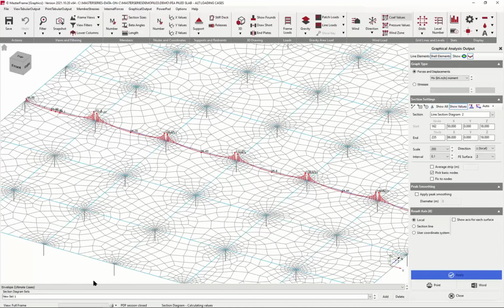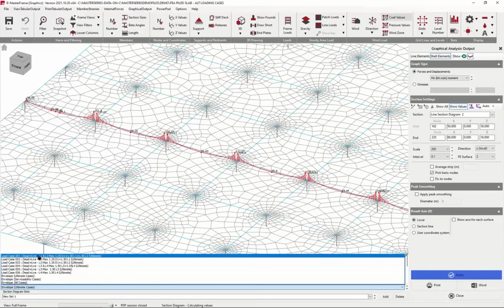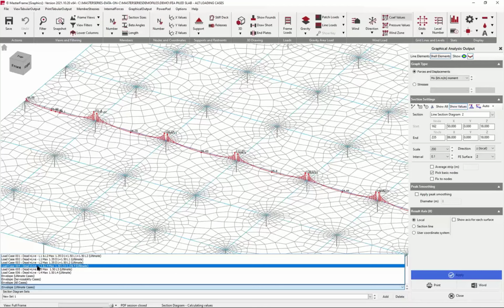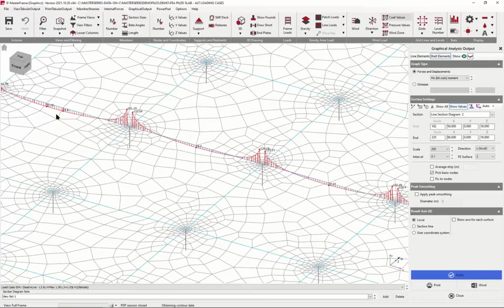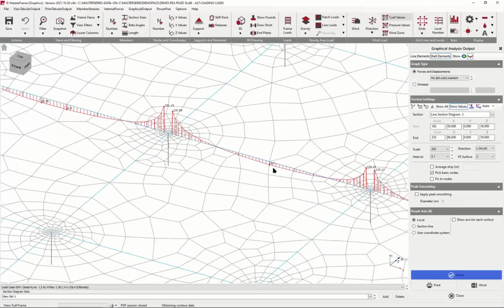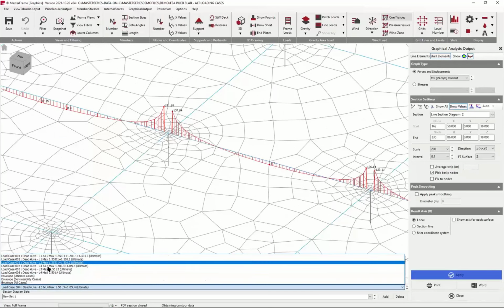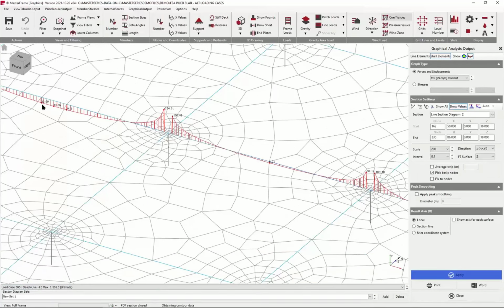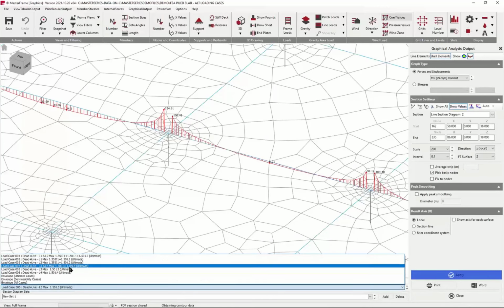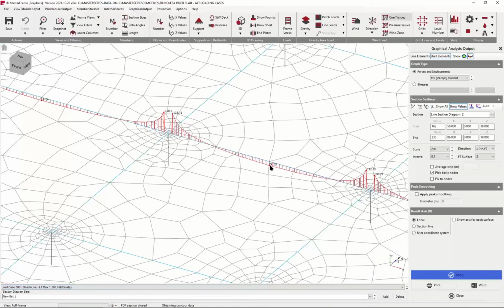you'll see that if I come from dead plus live ultimate, and it is coming in there 32 and 19, when I go to the next case, it's 33 and, well, that's the minimum. That's 24. And then, so 24 from 19 and 33 from 34. So with the lower live load on the structure, it's not as big a percentage change.